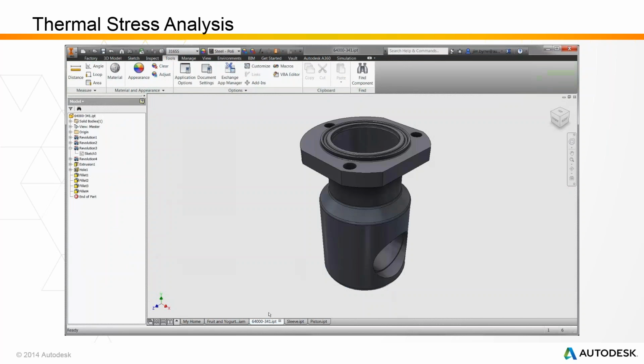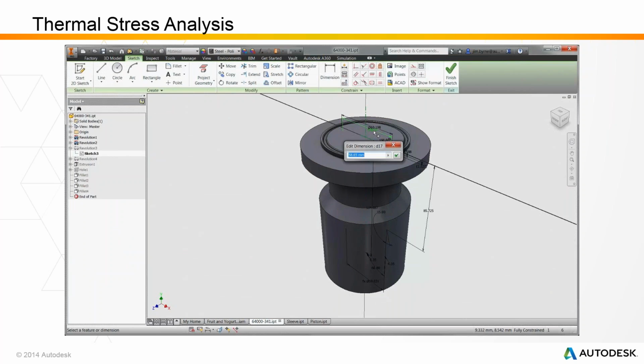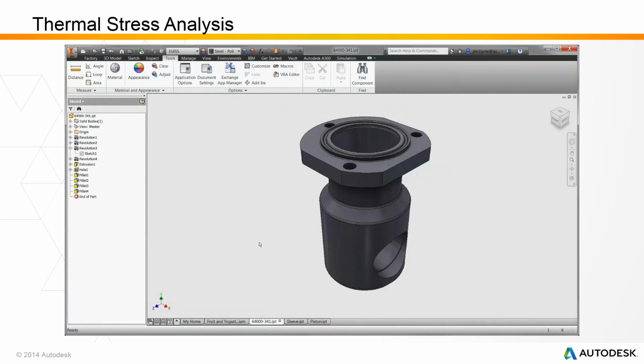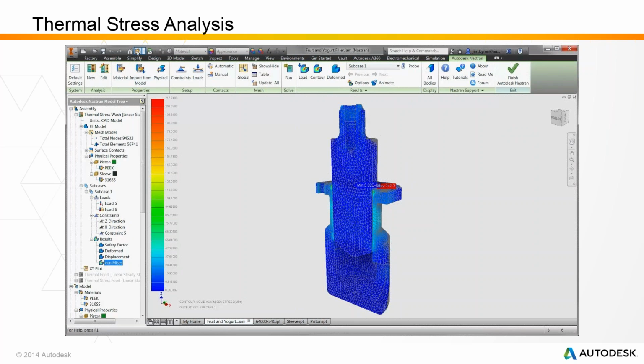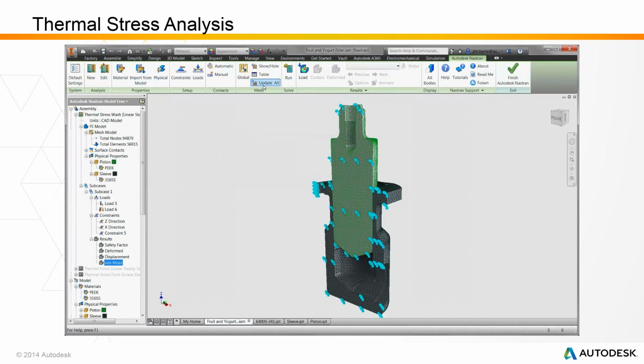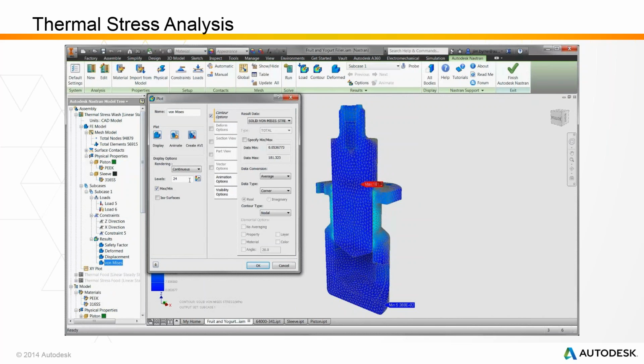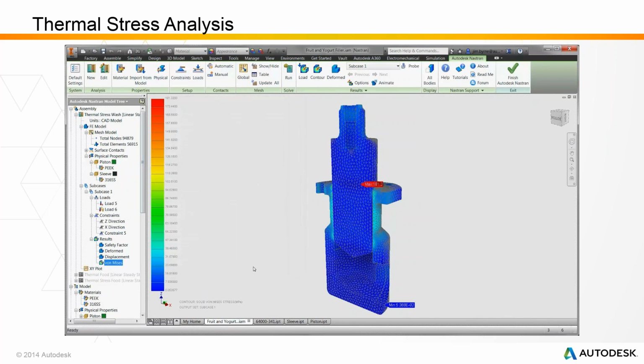So this is where we can now make a modification. We can go back to our piston design. Let's increase the bore diameter a little bit. We analyze. Let's update the meshing. Rerun the analysis. And again, we can check stresses and deflections. The stresses are now very low and now haven't got any interference. So this now will perform in service.